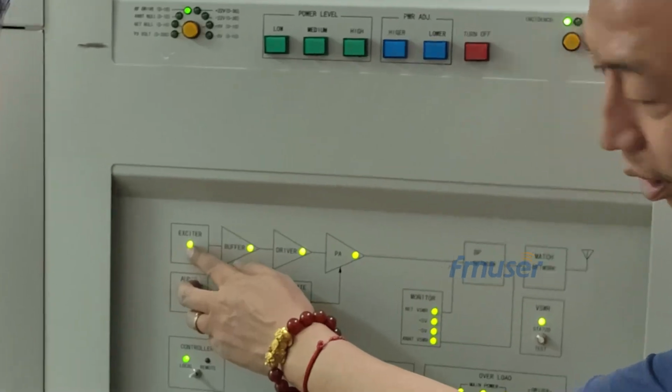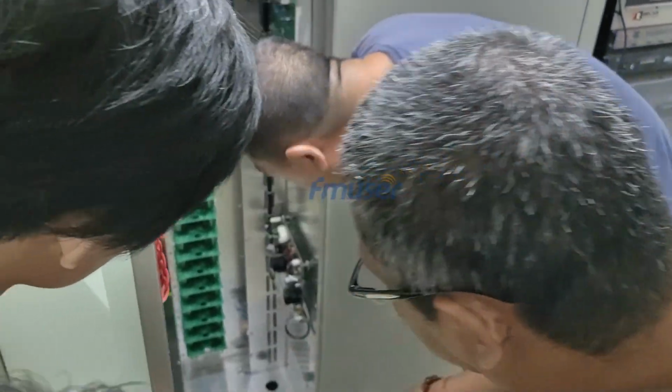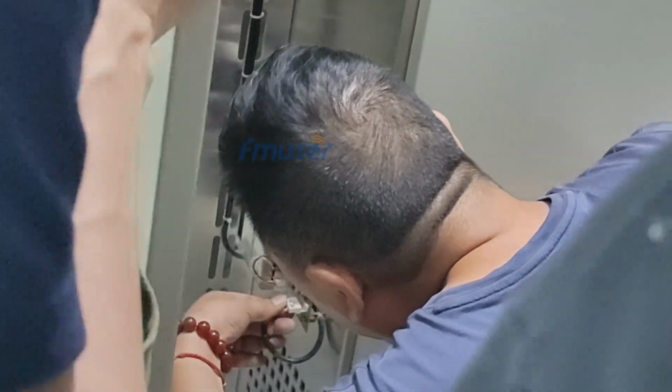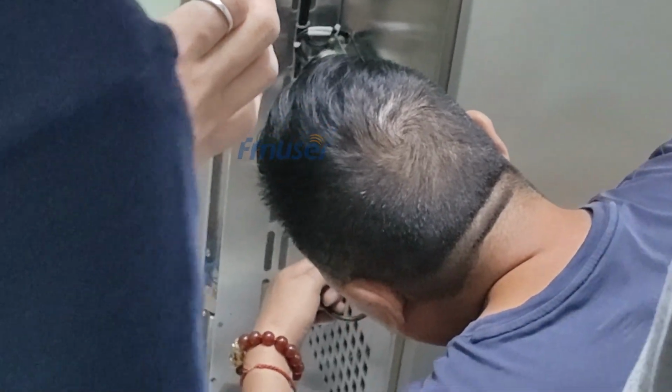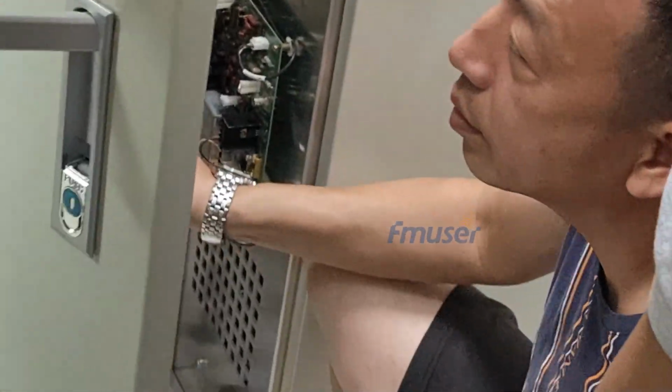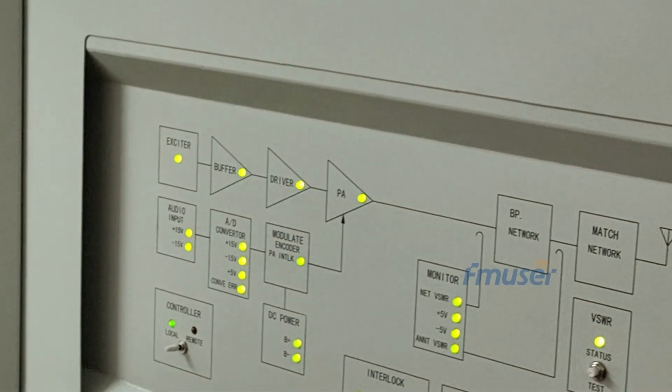Exciter troubleshooting. When the power supply of the exciter module is disconnected, it can result in the exciter not working properly. This is indicated by the exciter indicator light on the monitoring panel turning red. This light serves as a visual warning, alerting the operator to the issue and indicating the need to address the exciter troubleshooting. Ensuring the proper functioning of the exciter module is crucial for maintaining the overall performance and reliability of the